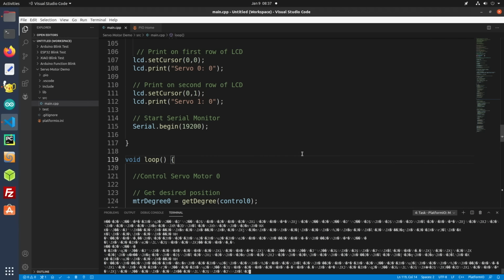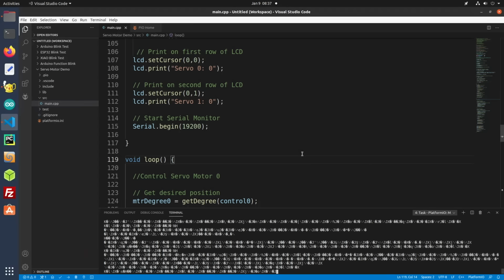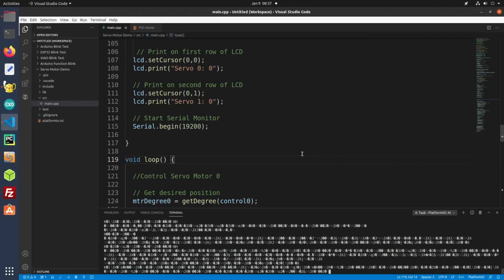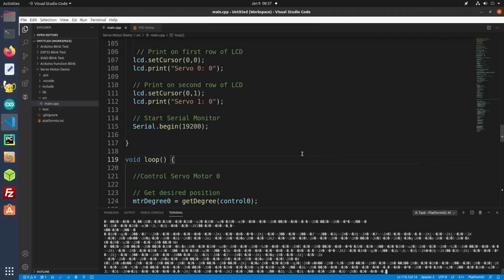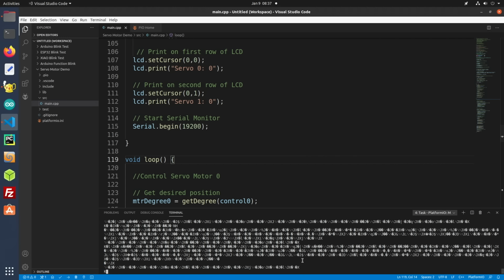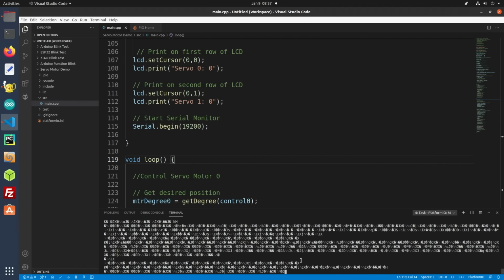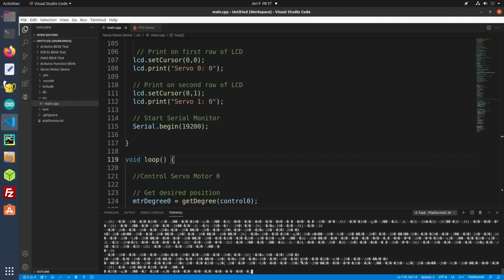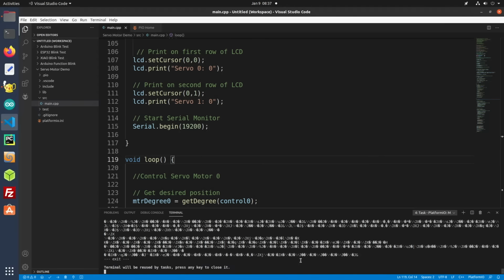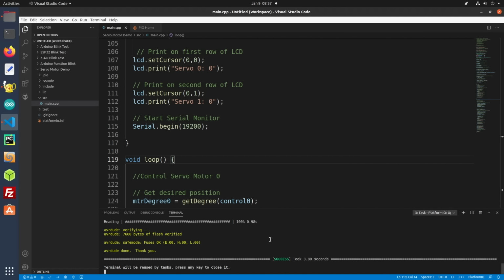Now, as I mentioned in the explainer earlier, the platformio.ini file contains all of the parameters specific to the project. Before we do that, this is getting a bit annoying at the bottom, so let's stop the serial monitor, which you can do with a Control-C, and then if you hit Enter, you'll be back into the terminal mode. Now, let's go and take a look at platformio.ini.